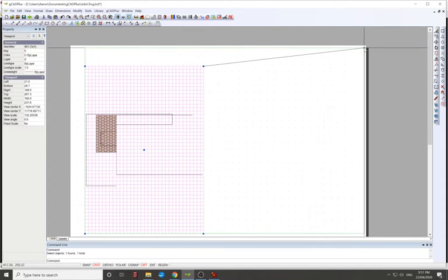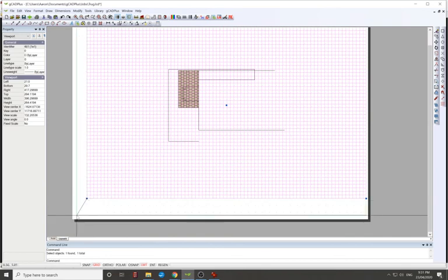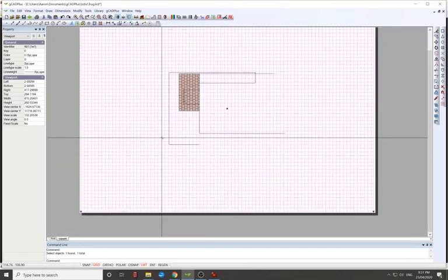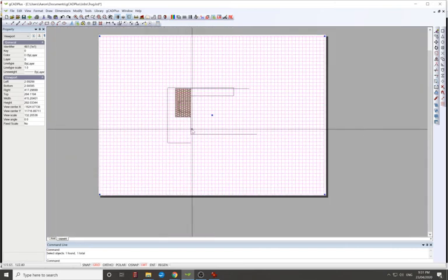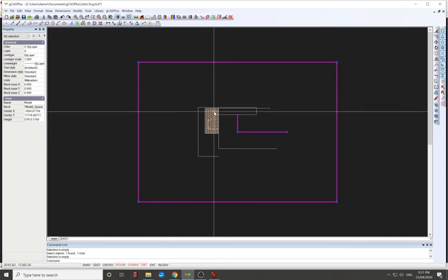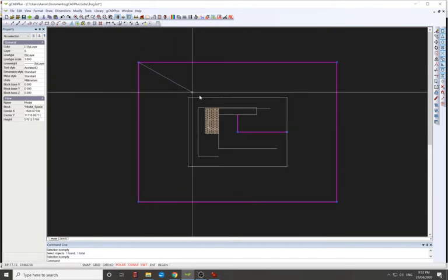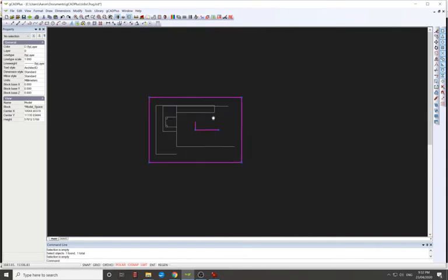So you want to open that viewport up, and I just roughly size it to there. But now that's out of proportion to the drawing itself. And all you do there is you just double click onto this. That movement wasn't anything to do with double clicking, it was just a movement from the mouse. And then you just change that viewport. Now you see the viewport in the model space, and you click it like that.